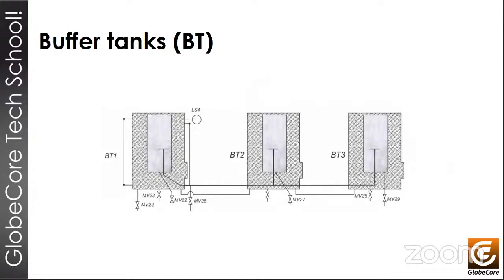Okay, these are buffer tanks. The buffer tanks are designed to contain oil, both for processes in which oil level may drop as a result of the regen process, and for the reactivation of the Fuller's earth. So there are actually two tanks inside one. You can see one external tank and one inside it, and that additional tank collects pollutants and water during the Fuller's earth reactivation process, basically condensate. So when the Fuller's earth reactivation process is over, the oil from the buffer tank returns back to the columns to prevent oil level from dropping in the transformer.